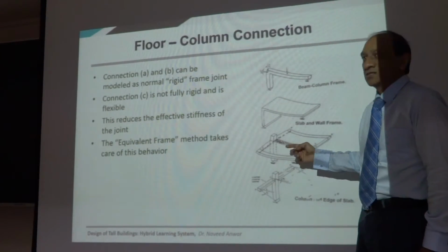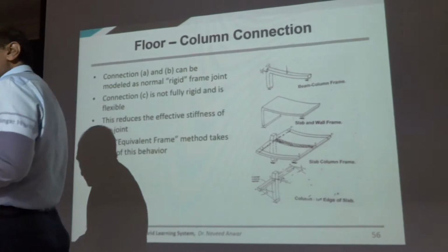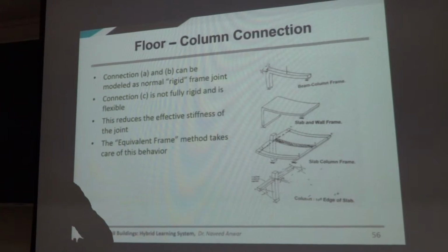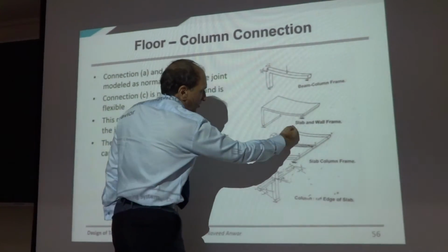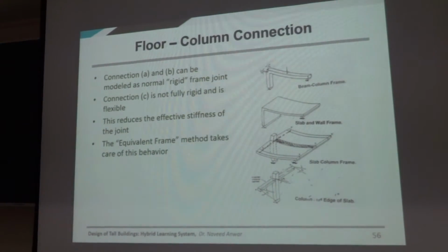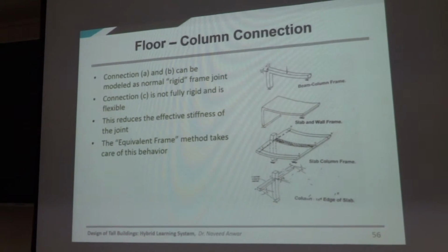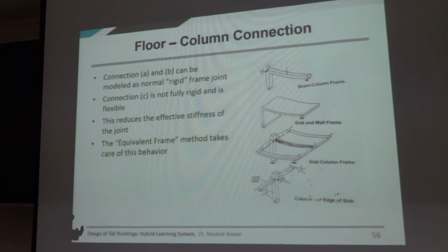So now that means there is going to be some leakage of stiffness. Some stiffness has leaked away into the torsional rotation here and transverse deformation there. Clear? So this must be taken into account while calculating the equivalent properties of the frame. So the relative stiffness of the column and the frame need to be adjusted. Basically, that's what we are saying.